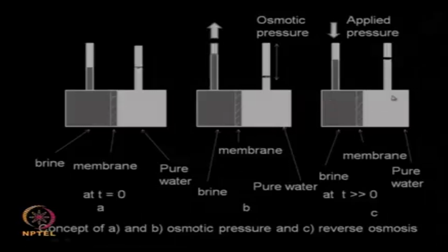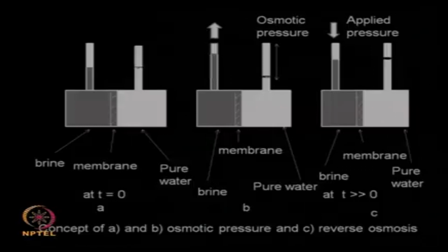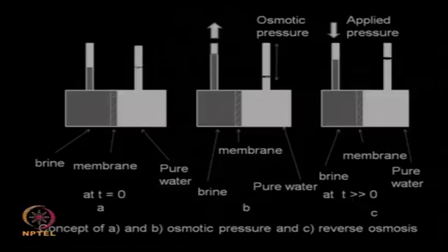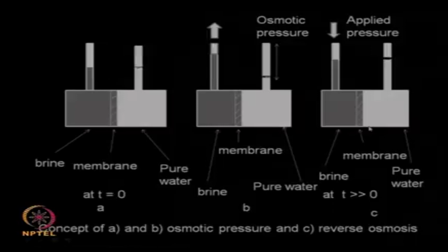the pure water region. So this portion will get more and more concentrated with salt, and finally at some point the pressure you have to apply will be so high that you need to discard this particular salt water. And this is the principle by which desalination of salt water works. There are now many places globally where pure water is produced using the desalination of seawater, especially in many countries in the Middle East, places where we cannot have bore wells. There reverse osmosis is used for getting pure drinking water from seawater.